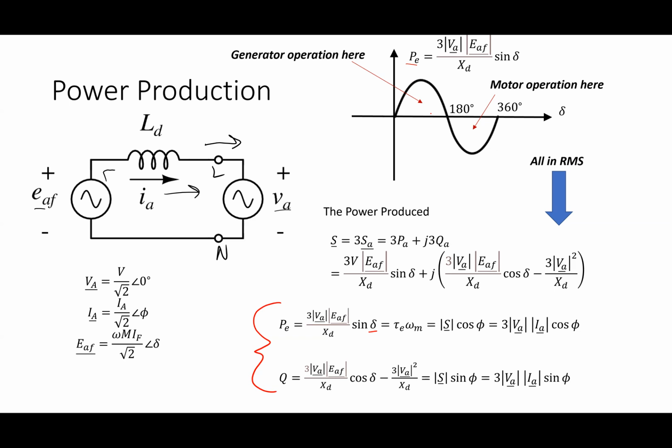Why is it different here? Why is power positive? What am I doing that's counter to that? Currents coming out of it, right? I basically treated this guy using the opposite of my passive sign convention. It's an active sign convention, but I'm doing it that way because he's a generator. So positive power means he's producing it.